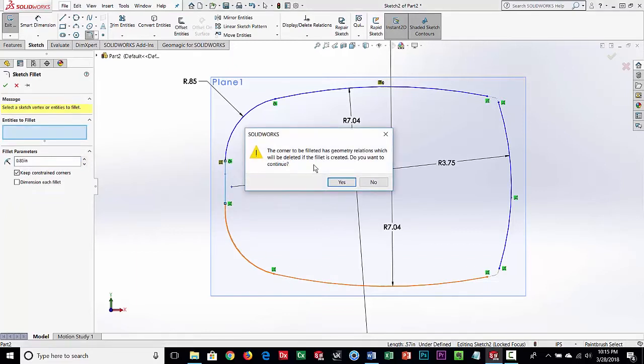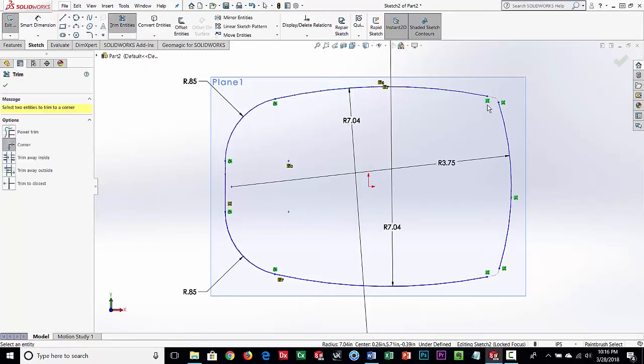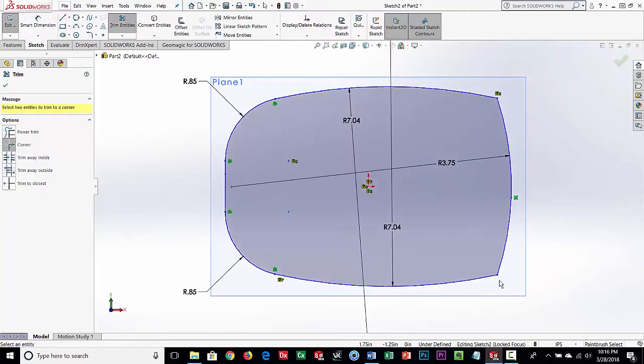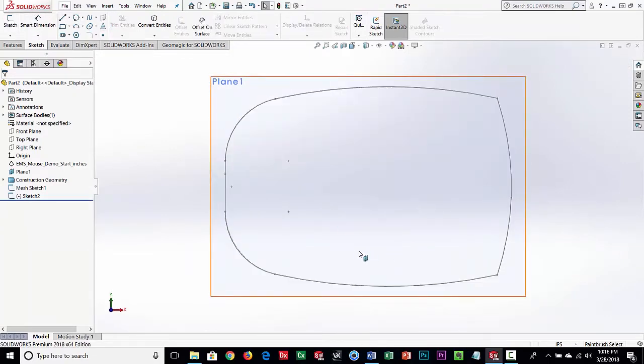Okay. And what I like to do is, the large fillets we'll go ahead and put in. But like I said, these small corners we don't want, because typically the part's been rounded off because it's old or worn. And if we do want fillets in there, we'll do that later, when it's a solid body. So the small ones I tend to just kind of model close to the corner and then just trim it out, okay? And again, we model the same way in Design X, and that's just a little bit of the technique. So in SolidWorks, once you have a closed sketch, you can see it shades it in, and we're basically done, and we exit the sketch, okay?